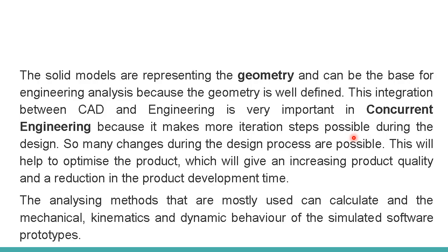So, the importance of solid modeling: the benefit is accuracy. All geometrical data, surface, angle and volume, are stored precisely in the system. If we need to make design changes, it can be done quickly without redrawing the entire model. The model can be directly used for simulation, stress analysis and motion study. Integration between CAD and analysis tools forms the base of concurrent engineering, where design and testing happen together. Ultimately, this speeds up development and gives a better quality product at lower cost.